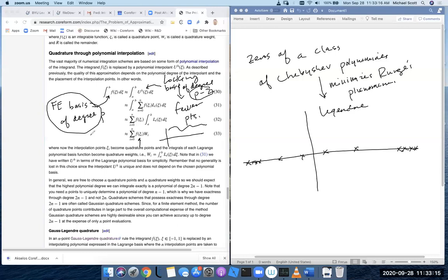So sometimes you'll take the strain and you'll split it, right? Maybe you'll split the strain into shear and bending and membrane. And then you'll do integration over the part that's giving you locking, and you'll do reduced order on shear.